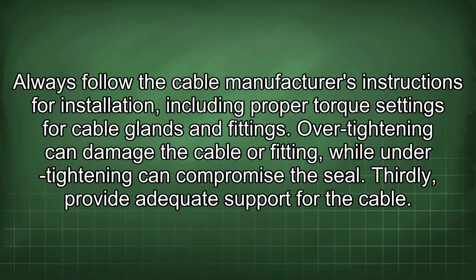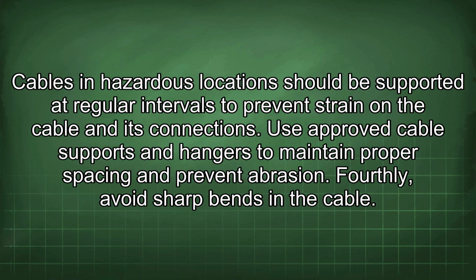Thirdly, provide adequate support for the cable. Cables in hazardous locations should be supported at regular intervals to prevent strain on the cable and its connections. Use approved cable supports and hangers to maintain proper spacing and prevent abrasion.